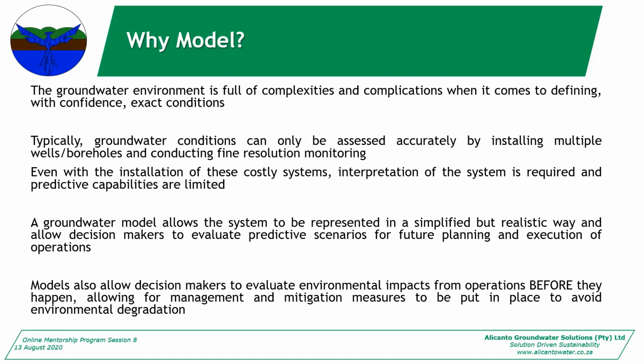So one of the key scenarios we run often for the mines in the EIA applications is to look at your waste rock dumps or your tailings dams or pollution control dams with a liner, without a liner, and to evaluate the clay liner versus a geotextile liner versus no liner. Then you look at your plume and you say, okay, economically this makes sense. You can evaluate different scenarios like that before they happen. Because monitoring is great, but monitoring doesn't allow you to prevent it from happening. It only allows you to react to it happening.